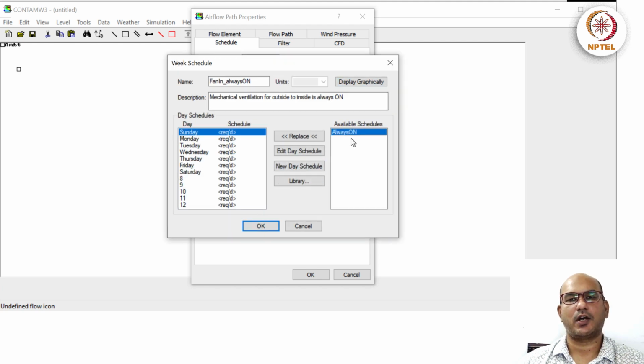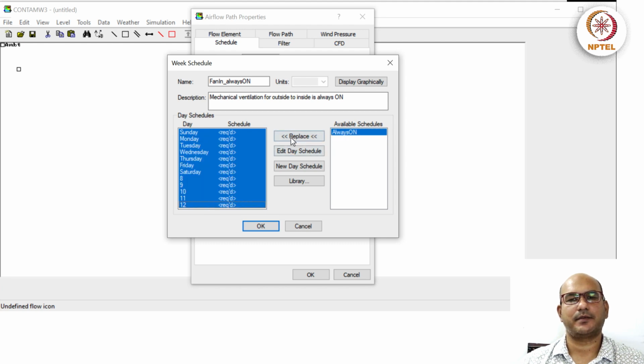Yes. So now this schedule is available, and this is the fan schedule. So we have to give this schedule to the schedule of the fan. So I will select always on and select all of them and say replace. So now you see the schedule of all the days is always on.